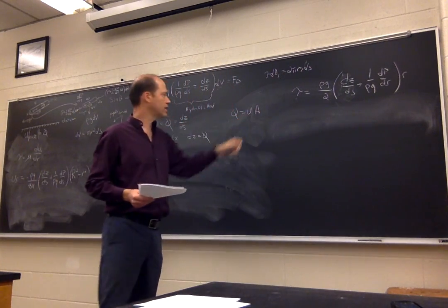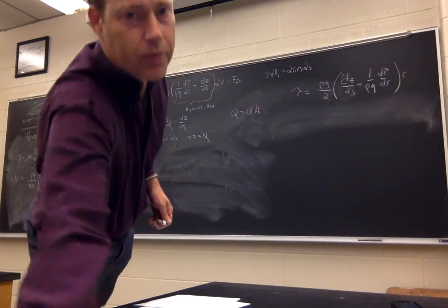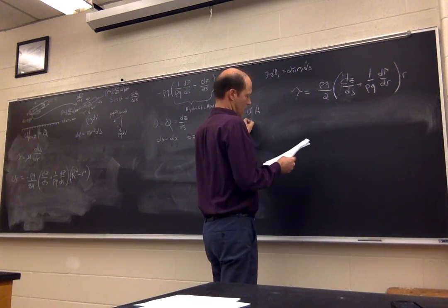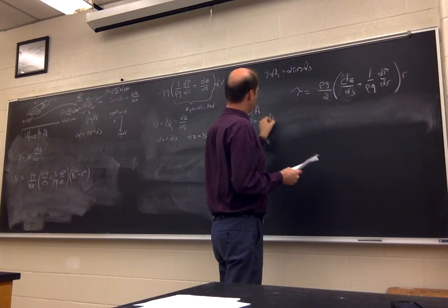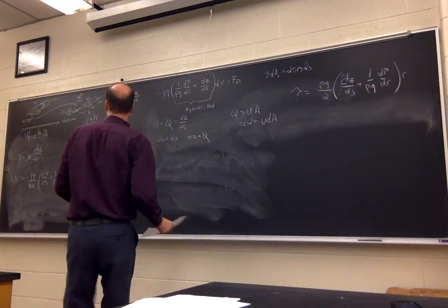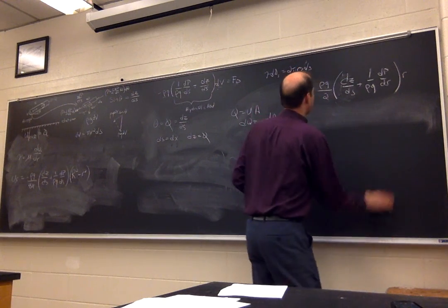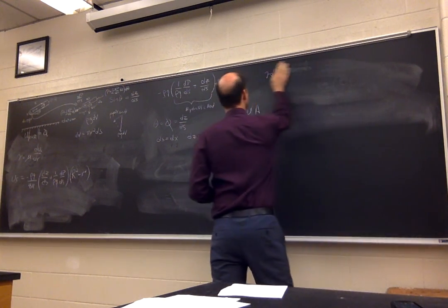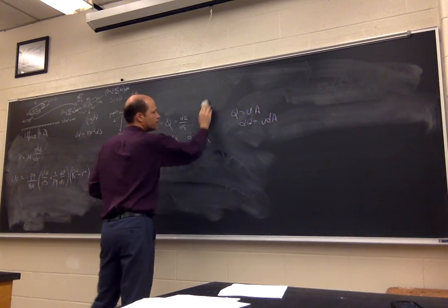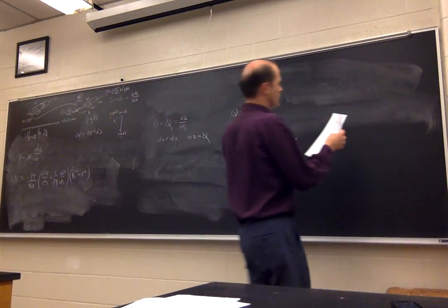The other thing is that, of course, we know that discharge is equal to the velocity times the area, so that the little piece of discharge, dq, is equal to the velocity times the little piece of area. So what we have to do in order to solve what the discharge is in this pipe, now that we've got a velocity profile solved, and I'm going to erase this, is we need to draw a second diagram that helps us understand what this looks like.